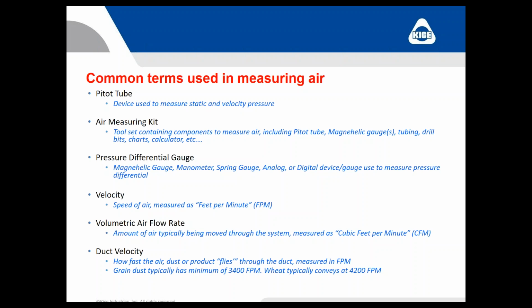Velocity, we're going to use that word a lot. Velocity basically is the speed of the air, and it's measured in feet per minute. So when I talk about velocity, I'm referring to the speed of the air measured in feet per minute. Volumetric airflow rate. Again, the short version is CFM, cubic feet per minute. How much air do I need to move, and at what velocity in feet per minute? And that's going to help me get to the results that I'm looking for.